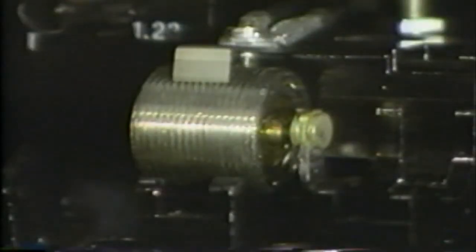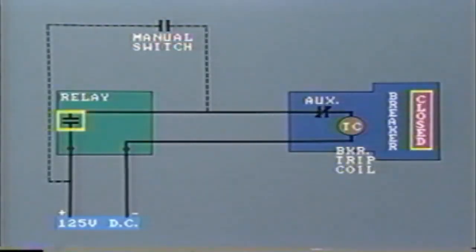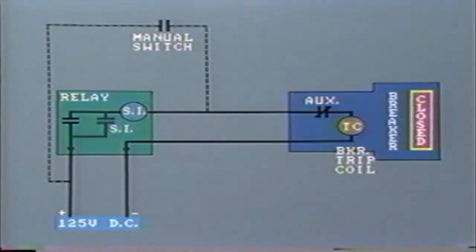But it is possible that the relay contacts may bounce open first as the fault is removed by opening the breaker. These delicate contacts inside the relay are not made to interrupt this relatively high current flow through the tripping circuit. So in order to protect the contact surfaces, a seal-in arrangement is usually wired into the relay.